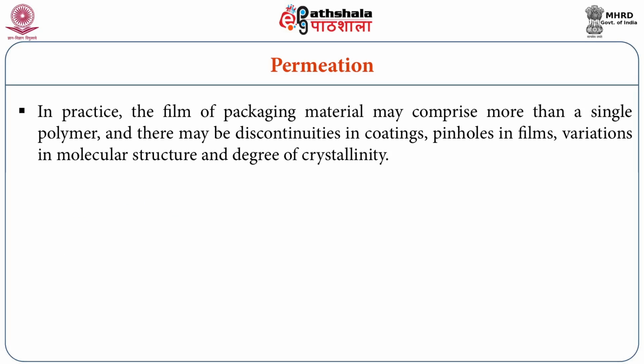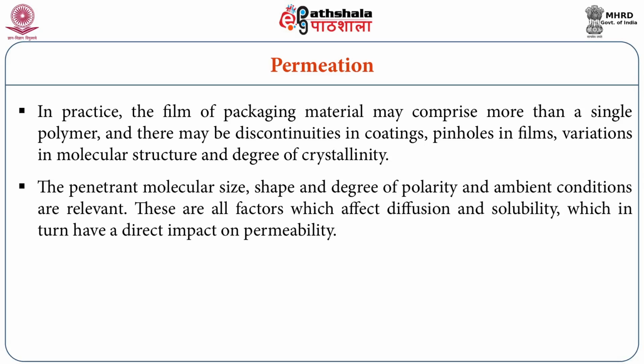In practice, the film of packaging material may comprise more than a single polymer, and there may be discontinuities in coatings, pinholes in films, and variation in molecular structure and degree of crystallinity. The penetrant molecular size, shape and degree of polarity, and ambient conditions are relevant. These are all factors which affect diffusion and solubility, which in turn have a direct impact on the permeability.